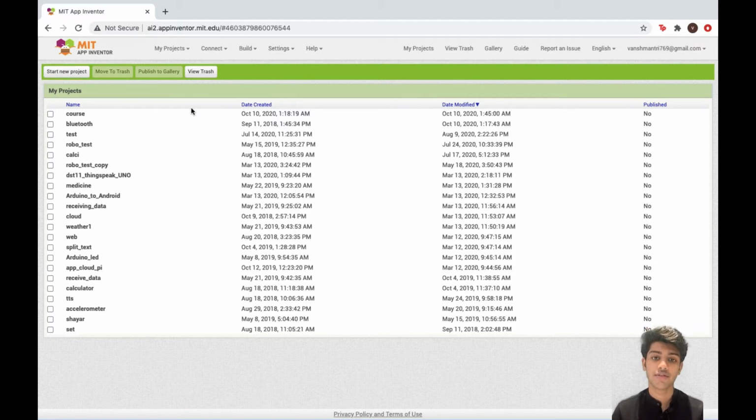So in order to achieve this, we will be requiring a Bluetooth module so that the connection between the Arduino Uno and the mobile application can be established. We will be using the HC05 Bluetooth module. Basically this module enables Bluetooth communication between the module and the smartphone, and then it can serially communicate this data with the Arduino. When we were studying serial communication, I gave you this very example and told you how the Bluetooth communication takes place. And this is what is happening over here. So I'll just repeat what I said then.